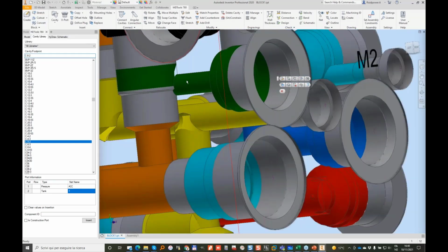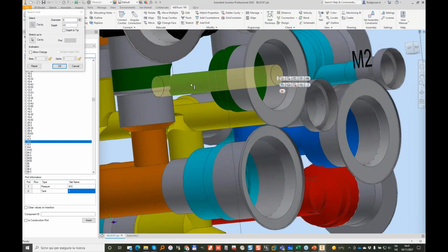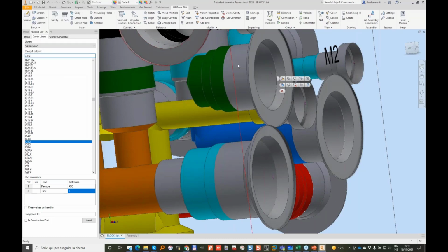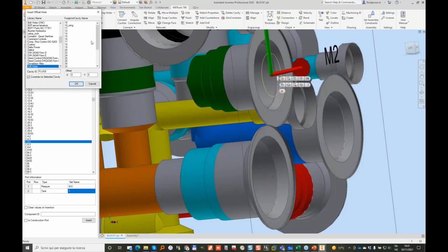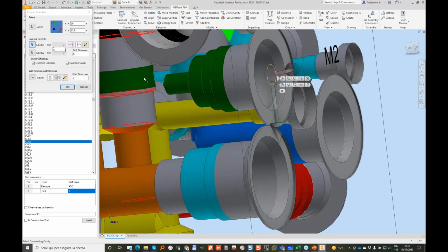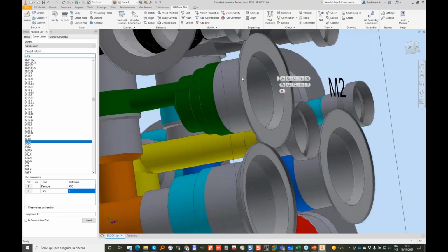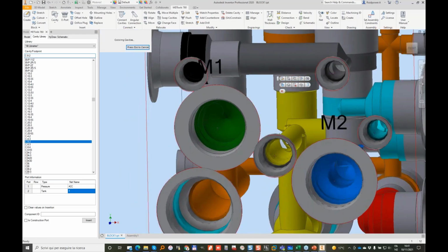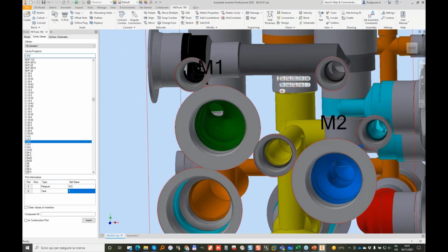So as you see now, there is a problem here. So I will stretch and reduce this drill. Well, let's make it a larger one. Let's make it 15 by 20. I'll make an offset hole on this cavity, and I take a 6 millimeter offset hole, and I connect only the offset hole to the port number 2. This is a technique, really, you can make offset connections, so a main drill and an offset hole, and this is working fine.